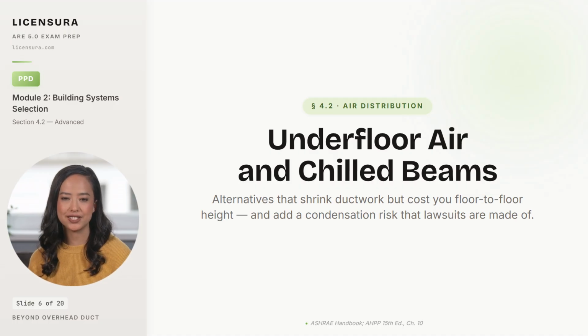Overhead ductwork is the default distribution method in U.S. construction, and the default is fine for 90% of projects. The other 10% are the ones the exam asks about. Underfloor air distribution moves the supply ductwork into a raised floor plenum and lets you punch floor diffusers wherever the tenant wants them. Active and passive chilled beams replace bulk ducted supply with a coil in the ceiling that does most of the cooling work locally. Both options reduce overhead ducting dramatically.